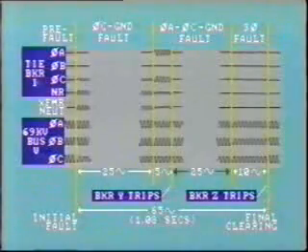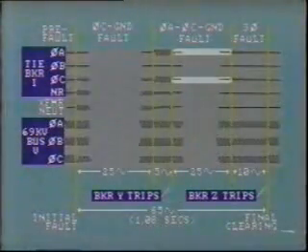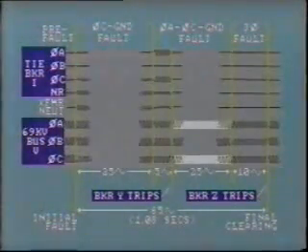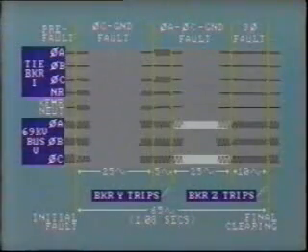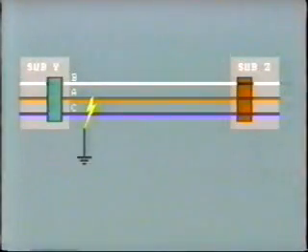For the next 25 cycles, we still have a double line-to-ground fault, but the current magnitudes are very much reduced because one end of the line is open. You can see that the A and C phase bus voltages are back to near normal. At this point, the fault again changes. The A phase conductor now burns open. The tree contacts B phase and falls to the ground.